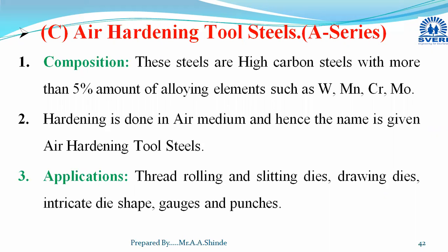If you compare water hardening, oil hardening, and air hardening, as we move from water to oil to air, their hardenability will increase, their distortion will decrease, and their wear resistance and hardness characteristics will improve.